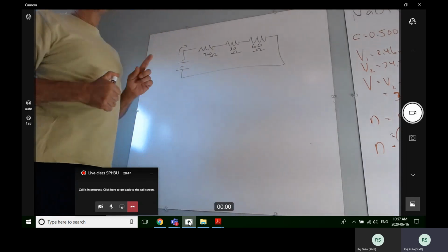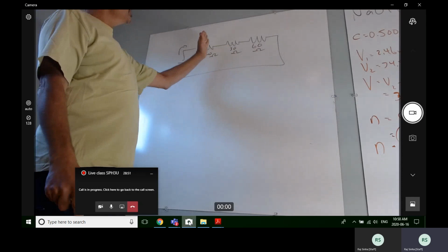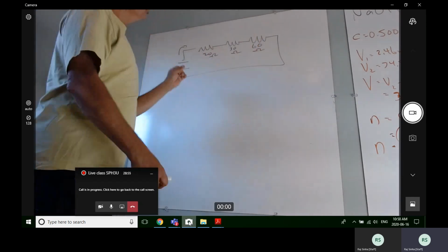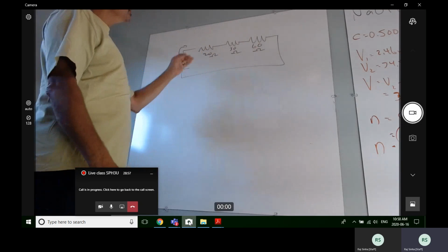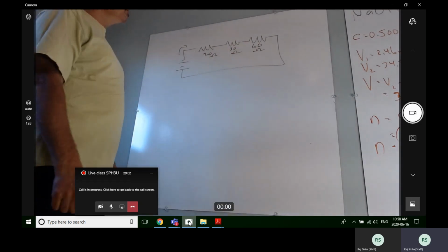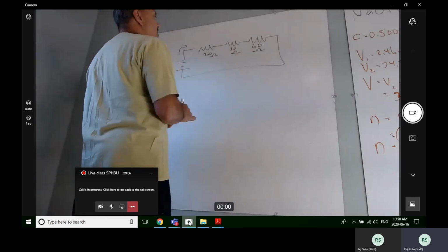So basically, and again, this is really important. If there's 20 and 30 and 60, I'm going to have some resistance, and I'm going to have to push harder to get through the next one. Then I'm going to have to push some more. So I'm having to push each step of the way, which means I'm using voltage at each step of the way to push through. And for resistors in series, remember, I add them up. So 20 and 30 and 60 is 110.